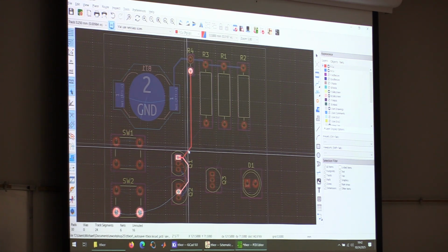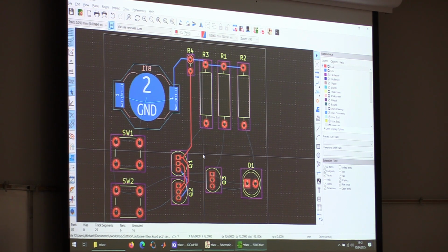Quick question. Is R4 really small because that's the one that was 470? No, I just switched the footprint to show how to update the board, but honestly, the resistors we chose here are massive for the application. Normally in the data sheet, it would specify the actual wattage that the resistor is able to handle, so the amount of current and voltage across it equates to power.